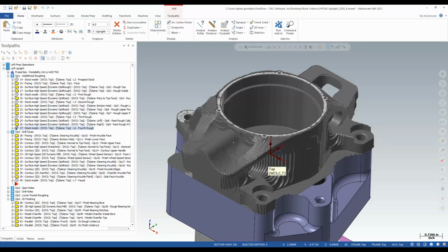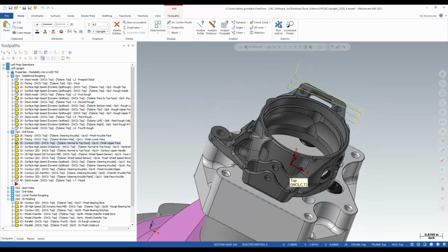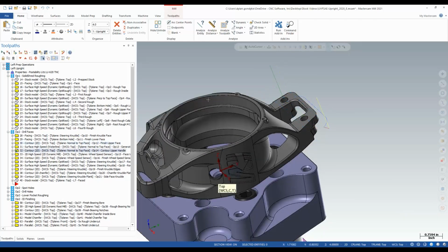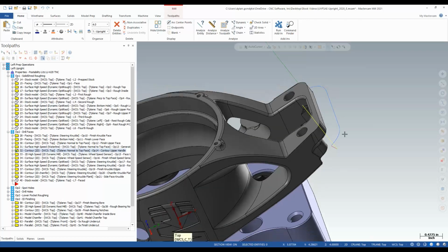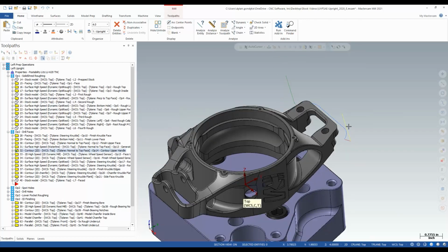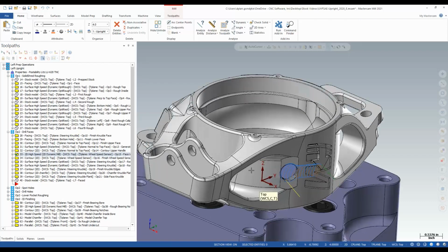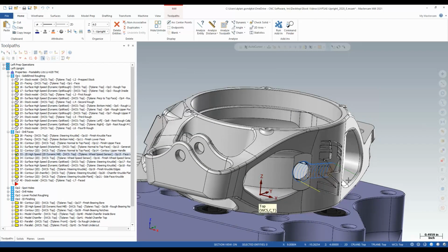You have the choice whether you want to create a new model to reference or not, and when you do so. You know, these contours here that finish up the last couple of thousandths off of these face profiles, that will never be useful to reference for another finish operation or another roughing operation. So we never have to calculate a stock model against them. And that's the choice we make as a programmer to intelligently build this stock reference into our programs.